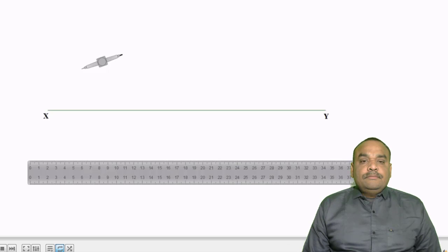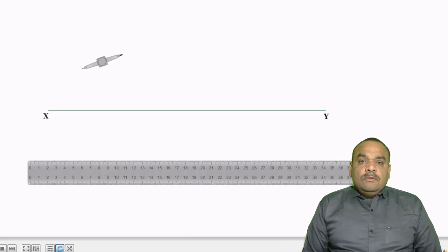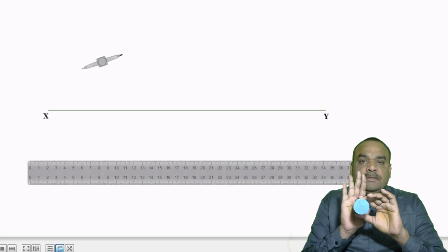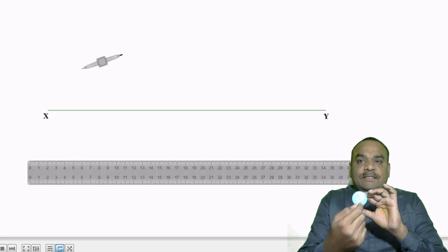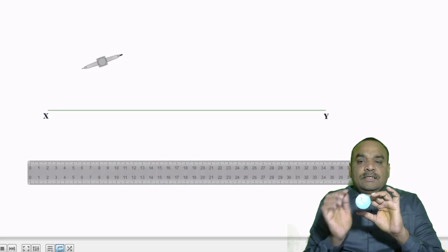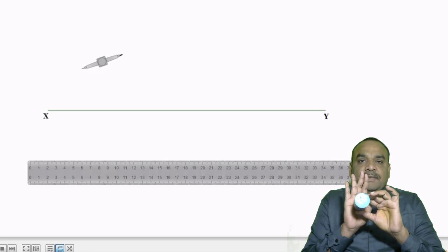In this problem, we have the cylinder and the base of the cylinder resting on VP plane with its axis perpendicular to VP. So now we have the cylinder and it is resting on VP plane. So your elevation becomes a circle, and the elevation of the cylinder is the true shape of the base, as it is resting on VP plane.